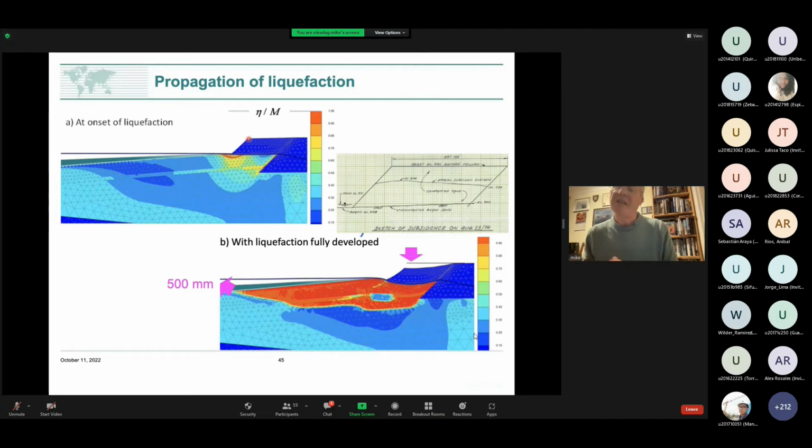So we're testing it against an instability criterion. And when we first trigger, it triggers right down here at the toe. And then, as you saw, everything develops. And what we computed when we stop, that actually is 4 meters. And even though I showed the limit here, we've actually got 500 millimeters of movement.